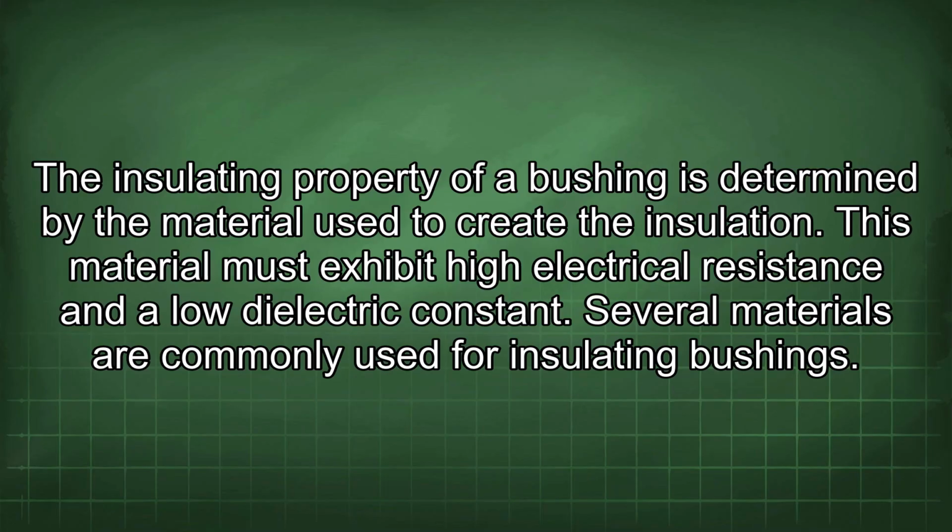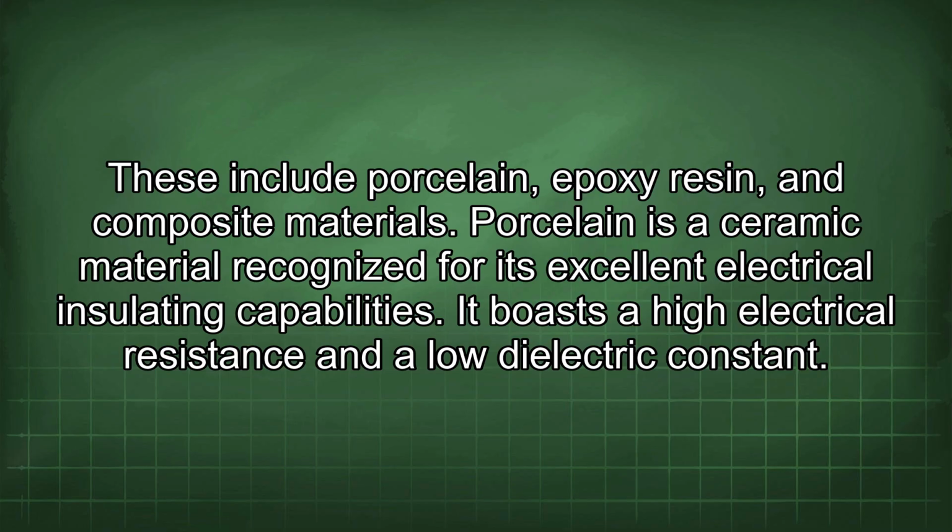The insulating property of a bushing is determined by the material used to create the insulation. This material must exhibit high electrical resistance and a low dielectric constant. Several materials are commonly used for insulating bushings. These include porcelain, epoxy resin, and composite materials.